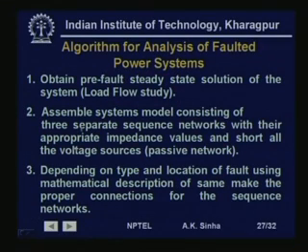But if we want to take into account the loaded system condition at which the fault has occurred, then we can of course do a load flow study and find out the voltage and currents in various parts of the system. So, we know the pre-fault steady state solution of the system by doing a load flow study.